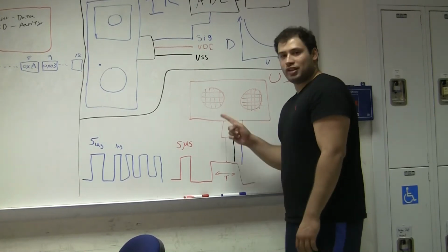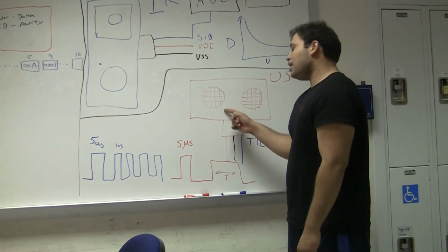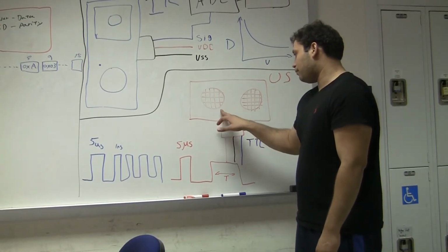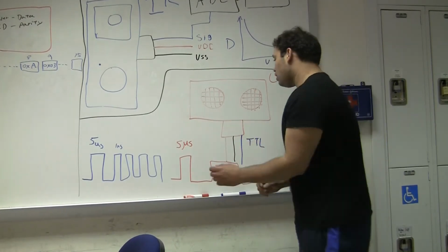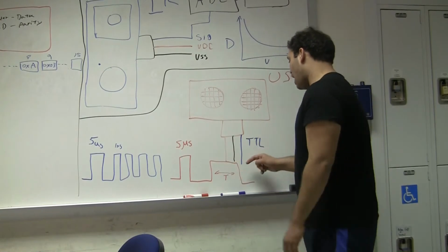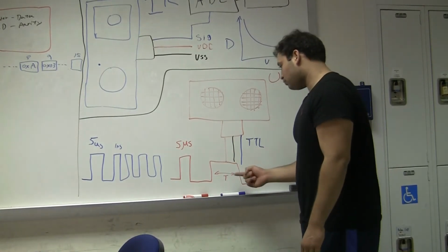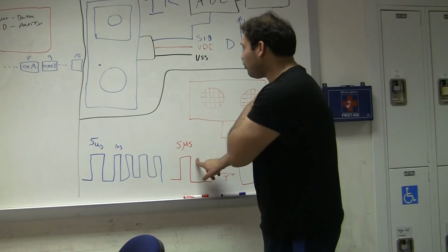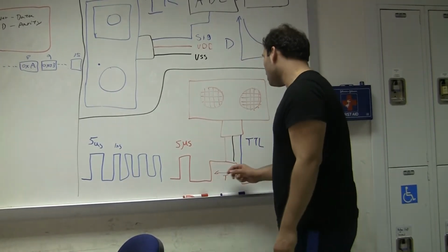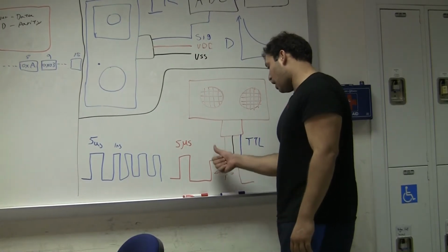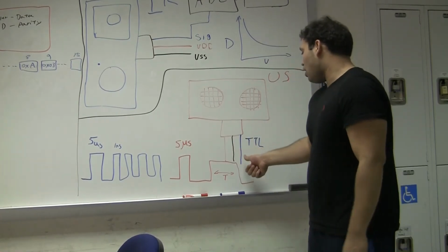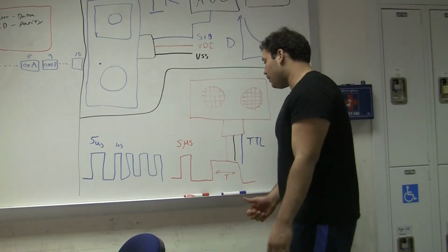The ultrasonic that we were supposed to use worked differently. It used sound to detect what was in front of it. It would emit an ultrasonic pulse and then time how long it took for that pulse to return. The way it worked was it was fed power and ground from the PIC, and it had a bidirectional TTL pin. We would drive the pin high for 5 microseconds, and then after a hold time of about 750 microseconds, the TTL pin would show a rising edge. When the pulse would return, there would be a falling edge on the TTL pin.